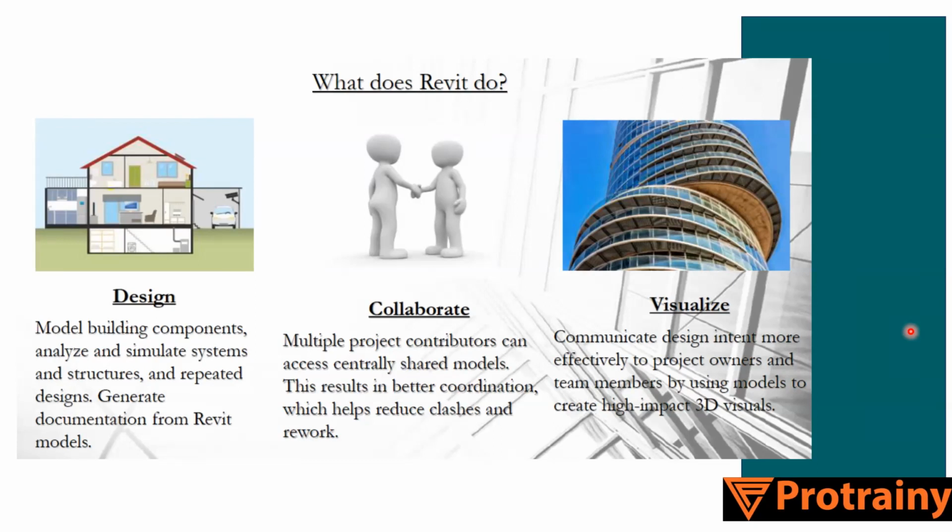But in this Revit software, you don't need to do that kind of donkey work, because if you make a simple change to a column in your plan, it will simultaneously change in all the elevations, your sections, your views, or any kind of calculation as well. The numbering of the column, maybe the calculation of your estimation, from everywhere that column is going to be removed. So it's of course a collaboration which happens within the software, as well as for the people who are working together.